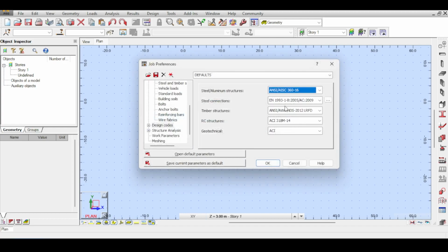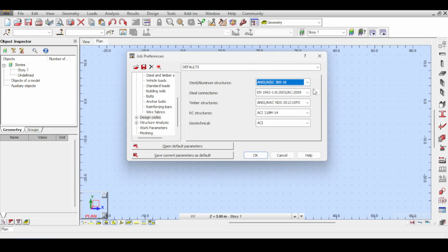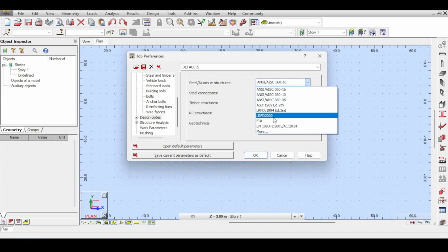Now, any Eurocode should be working. The difference between the codes is minor because each country can apply or change some equations based on their national annexes. You see, the Eurocode is basically a skeleton code that works fine on its own, but the countries in Europe can change some of the values and some of the parameters and even equations as a whole to fit their national needs. It's a really cool document. Anyway, so I'll just select here the Eurocode.